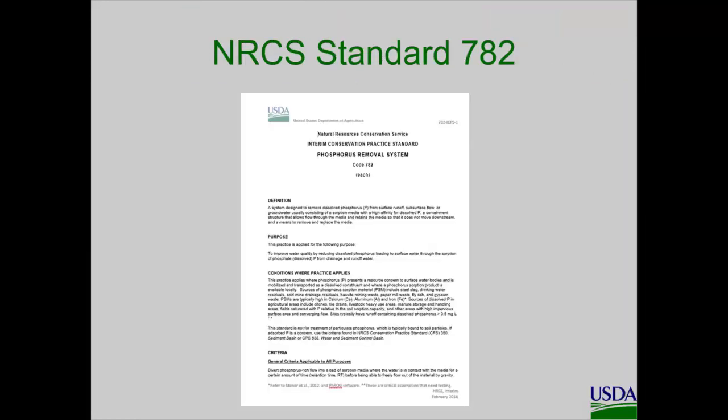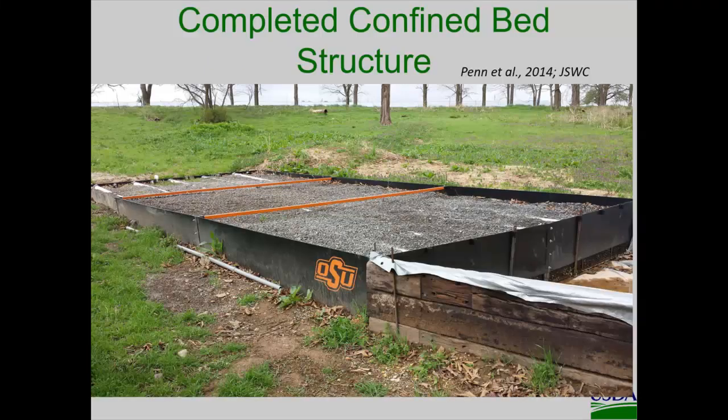I will say this. It is interesting. You look at the Ohio H2O list of practices, right? I'm going to back up, talk a little about just dissolved P in general. You look at those list of practices, and we see a lot of things that are great for particulate P, but many of them are not going to do squat for dissolved P. Your two-stage ditches, buffer strips, cover crops, all these things. They do nothing for dissolved phosphorus, all right? But I don't know who made that decision, but yet we don't see dissolved phosphorus removal structures on that list. I don't know. They didn't ask me.